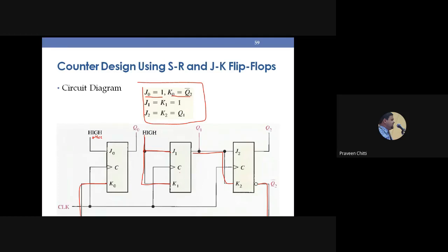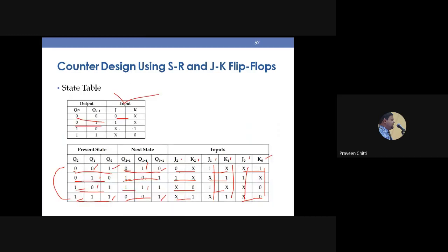Right. The important thing here is you should know how to write this particular table, which we call a synthesis table of the counter. You have to write the present state. Only 4 I have shown, remaining I have not shown for simplicity. Remaining, if you encounter, you have to write the next flip-flop inputs as don't care, because for the remaining 4 cases, the next state will be don't care, because we are not going to use those 4 states. Only these 4 states are used, right?